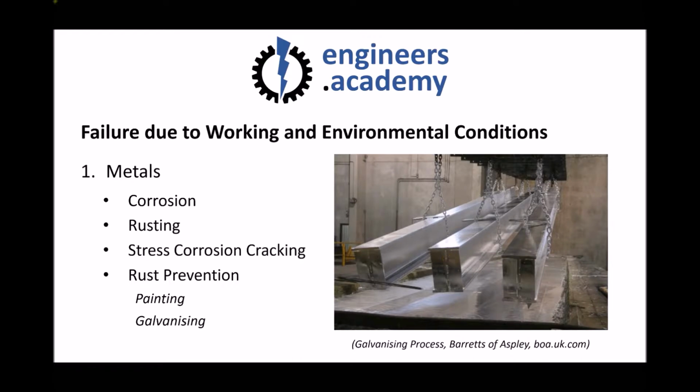The interesting thing, however, is that zinc is more corrosive than steel. The zinc will actually oxidize, and after oxidizing, a carbonate layer will form due to reactions with carbon dioxide in the air. But this brings us back full circle to copper, because zinc carbonate, as with copper carbonate, is actually corrosion resistant. So in effect, the steel is coated with zinc, the zinc corrodes eventually to form zinc carbonate, and what we end up with is a non-corrosive surface to our steel component. So the zinc is actually sacrificed in order to form a non-corrosive surface.